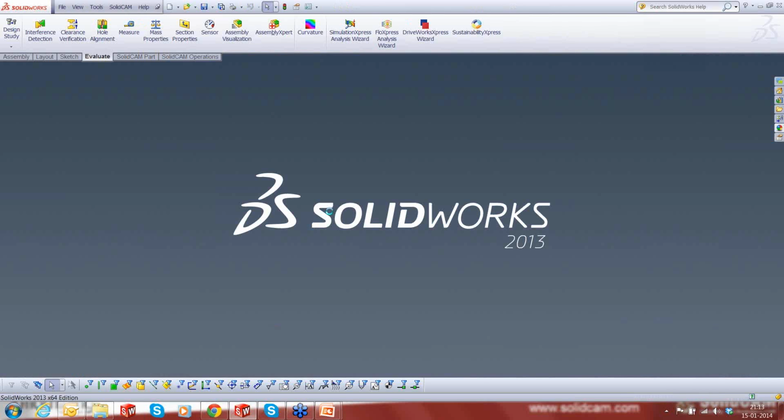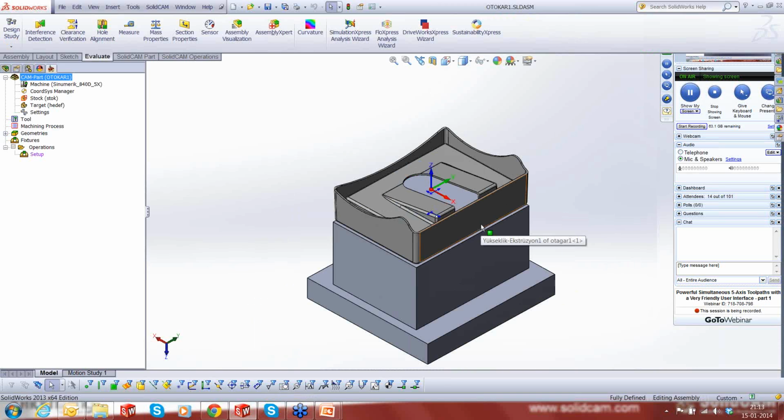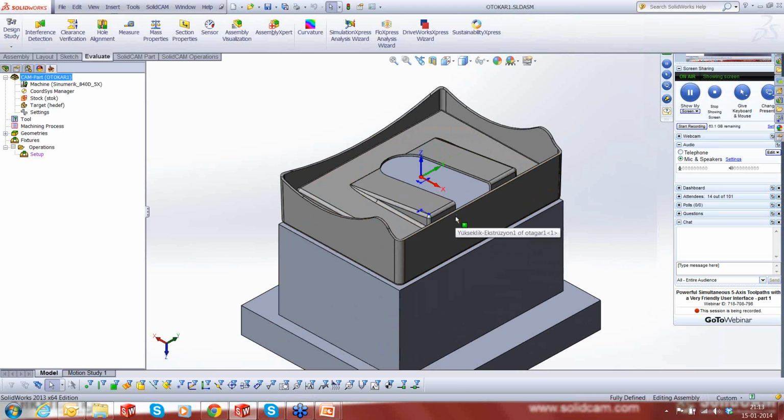Right. So we have this part out here, which is mounted on a holding fixture, and we are supposed to trim the outer edge of the part. Because in vacuum form parts, you can't get this edge. This has to be done using a milling process, a 5-axis milling process. It's also the same for some aerospace formed components which are done on a sheet. They have to be trimmed.